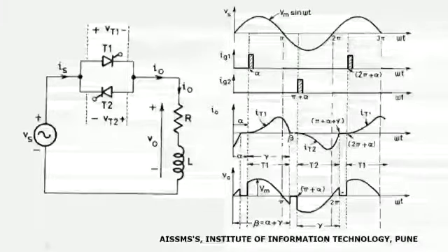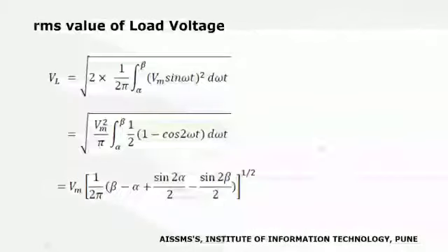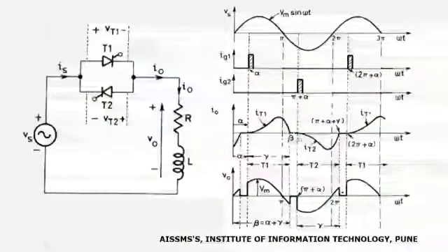Now the current starts flowing from the source through the load through T2 back towards the source. So with this, the direction of current through the load will get reversed, and the voltage appearing across the load will get reversed. So when T2 starts conducting, as the load is having an inductor, the current flowing through the load will increase gradually, and the direction of current is reverse. With this, a reverse voltage starts appearing across the load.